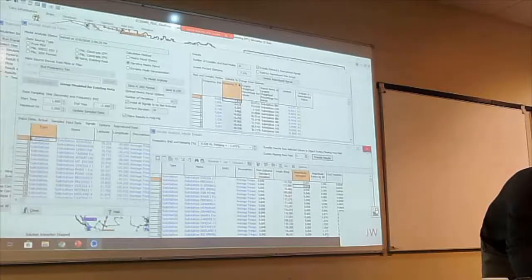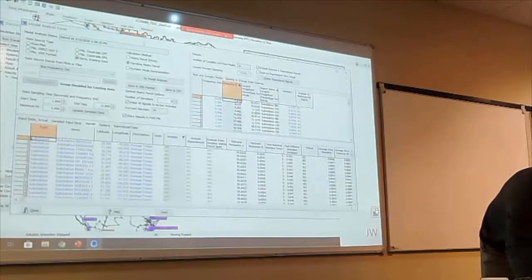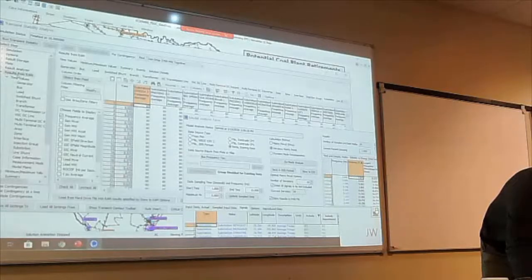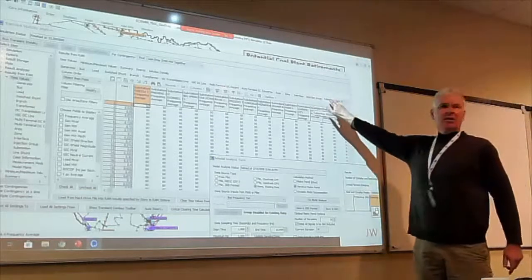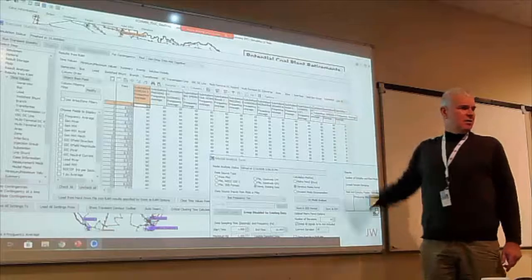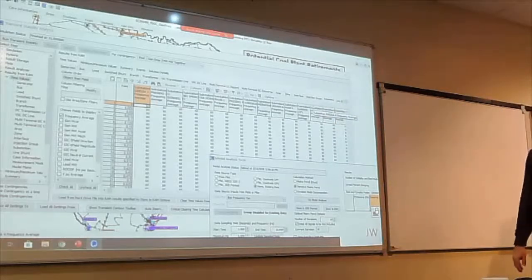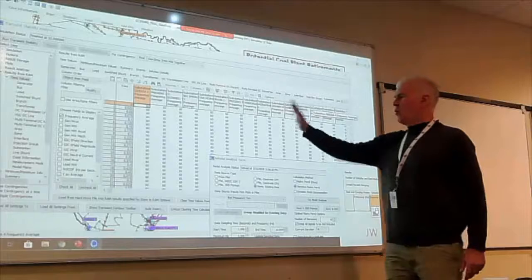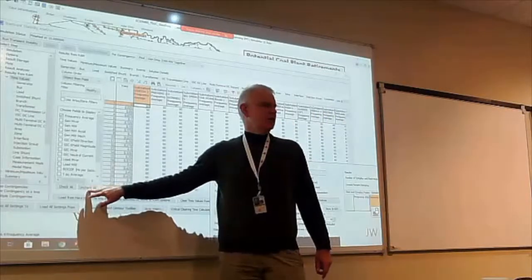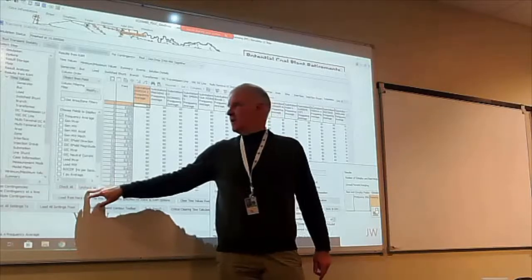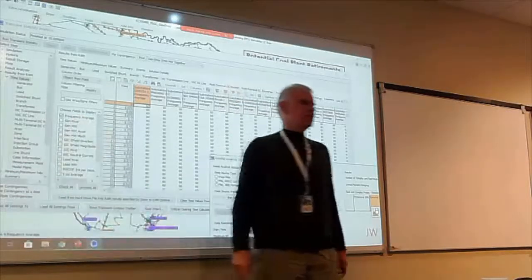If you go to results from RAM here. Results from RAM. Okay. Then I stored results for the substation. Go over to the substation tab, which is right there. Okay. Then you'll have a whole bunch of fields. Over here where it says uncheck all, uncheck all of them. Okay. And then just check the top one, which is frequency average.